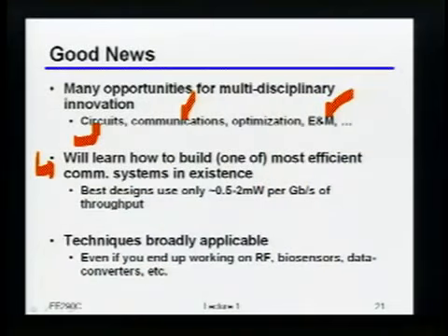Okay, so let's write this down to help you guys out. If I'm doing about half a watt, and let's be generous, let's call that 500 megabits per second, which is half a gigabit per second. How many picojoules per bit is that? Or let's do it a different way: how many milliwatts per gigabit per second is that? Is it 1,000? Yeah, actually you're right. It's about 1,000 milliwatts per gigabit per second. In other words, for those of you who like energy per bit, that's about a nanojoule per bit. Okay, so 3 orders of magnitude difference.